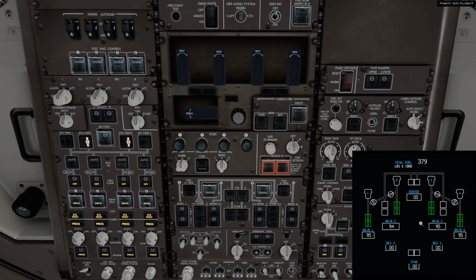If we have more than 120,000 pounds of fuel, turn on all pumps for tanks that contain fuel, turn on the override pumps and open the 1 and 4 crossfeeds. These two situations cover the whole range of fuel loads from full to minimum fuel. If you have the original fuel system installed via the PMDG equipment settings, you'll have to manage this panel in flight.